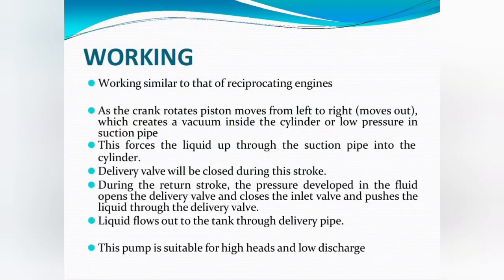So the working. As the crank rotates, piston moves from left to right, moves out, which creates a vacuum inside the cylinder or low pressure in the suction pipe. This forces the liquid through the suction pipe into the cylinder. Delivery valve will be closed during this stroke.